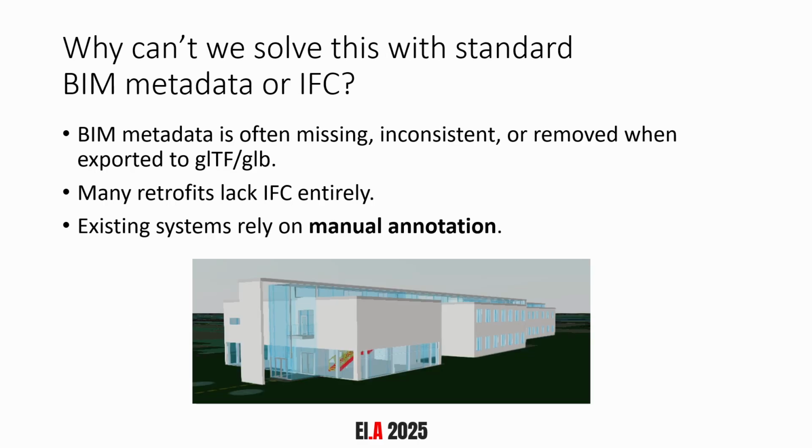So why can't we use BIM metadata or IFC? What we usually see out in the industry is that the BIM metadata is simply missing or inconsistent, or removed when we're exporting to more flexible formats, for example GLTF or GLB. Many retrofits lack IFC entirely, so there's no model at all. And existing systems rely on manual annotation, which is very common. So we want something that's automatic and reproducible in many 3D models.